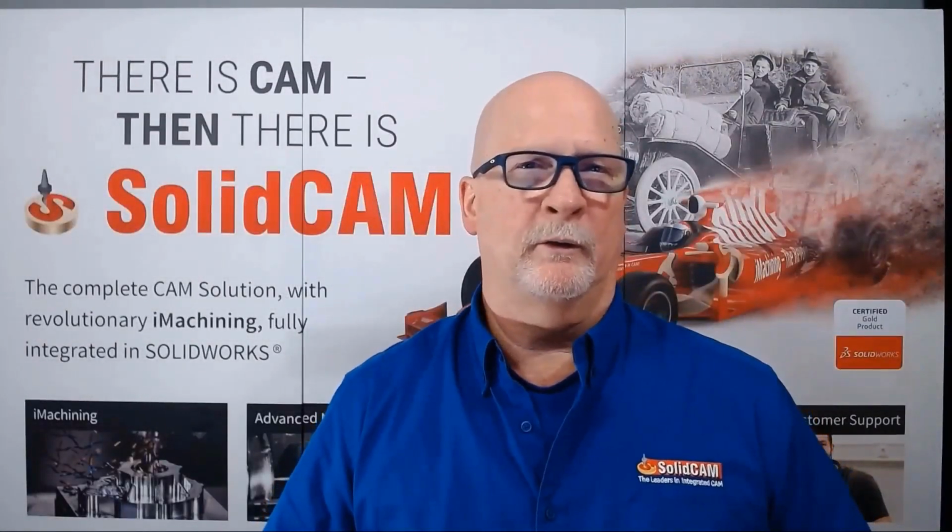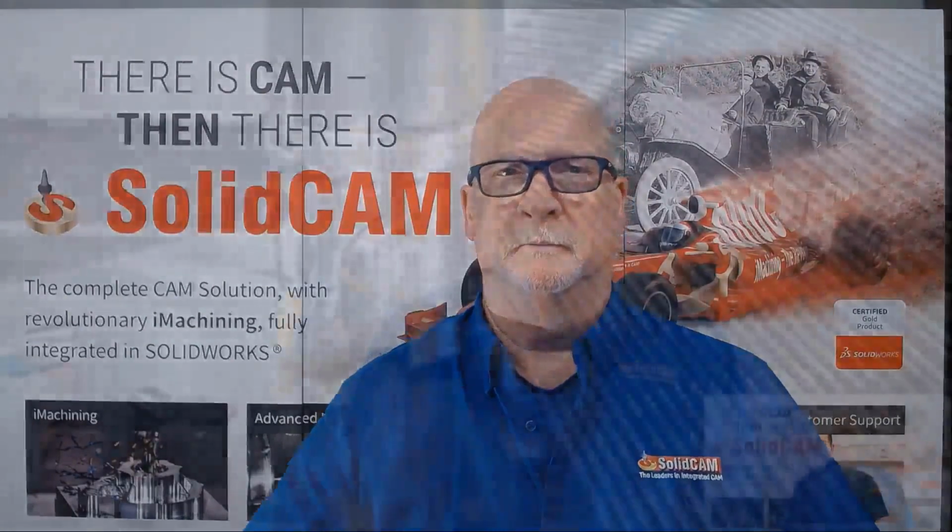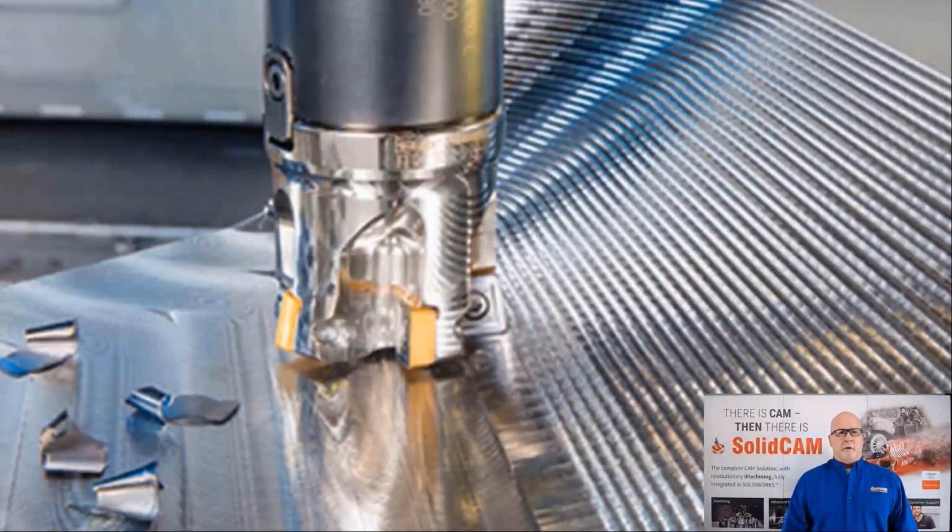So how does SolidCAM's iMachining compare with what they call high feed milling? Let's take a look. This image shows the in-process result of a toolpath that is generally referred to as high feed milling. The style of toolpath is based around very shallow depths of cut, using up to 80% of the diameter of the tool for radial step over, and using much higher spindle speeds and feed rates than would be used in a traditional, or what we might call an old school pocket operation.